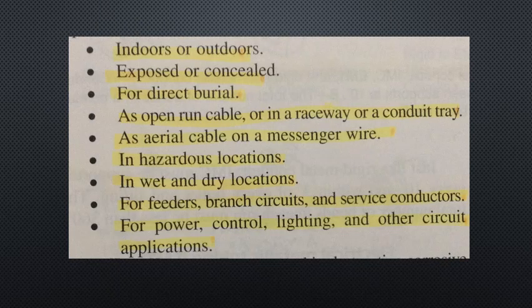Metal clad cable, or MC. This type of cable is a heavy-duty commercial and industrial assembly consisting of one or more conductors individually insulated and enclosed in an interlocked metallic armor that consists of corrugated tubing or interlocking tape. This type of cable looks similar to armored cable or BX. MC cable is available in sizes 14 AWG up to 1000 kcmils.